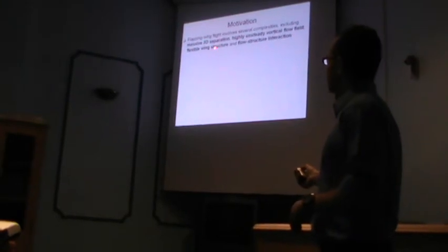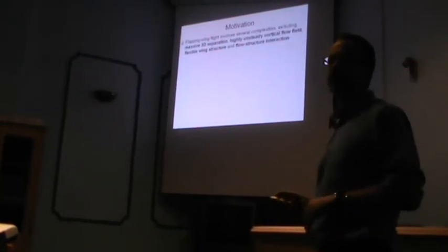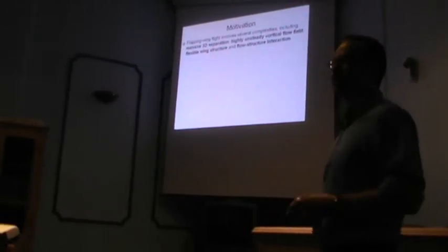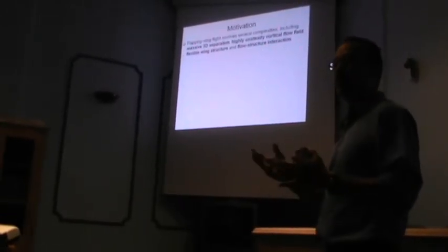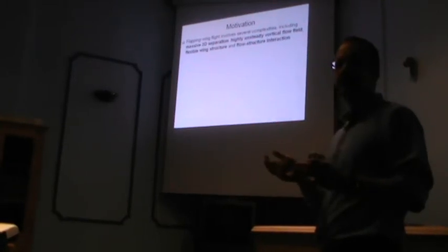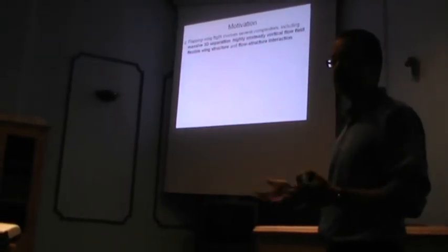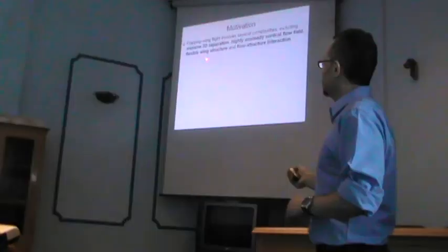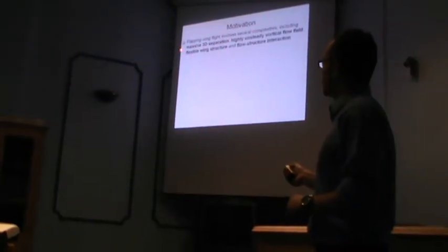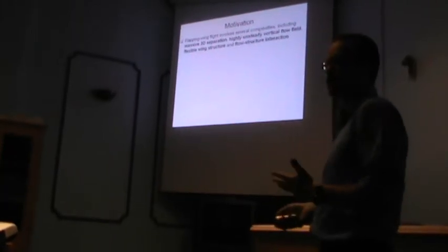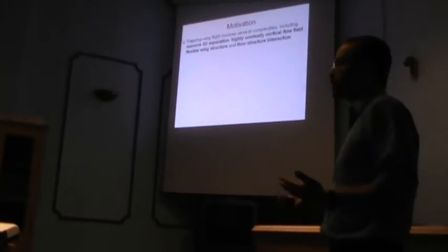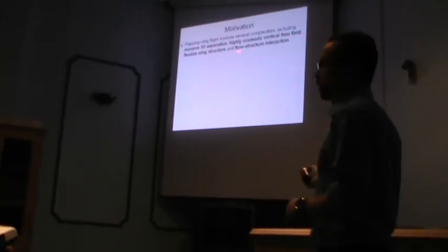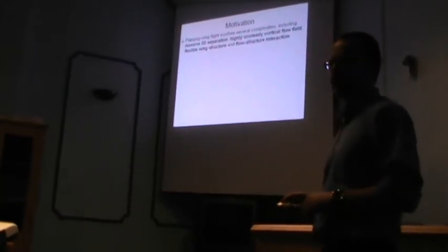You are talking about massive three-dimensional separation. The separated shear layers roll up into large-scale organized vortices that dominate the unsteady forces on these wings. In addition, similar to birds, you might want to make these wings flexible because there are certain advantages. And if you make the wings flexible, you go into a different kind of problem where you have to worry about flow-structure interaction.